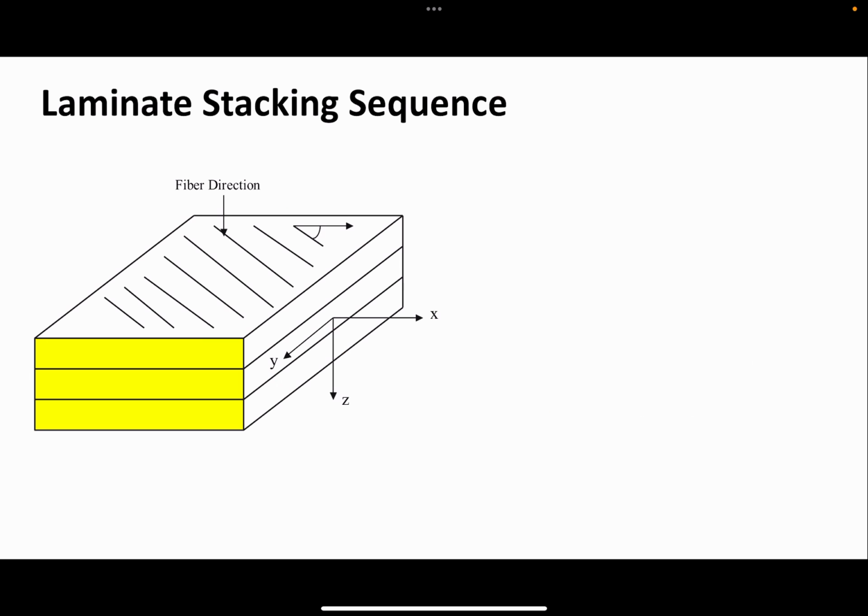What happens if you have an odd number of plies, where you have 0, minus 45, 60, the 60 does not repeat, minus 45 and 0? It is still symmetric about this plane, correct? So then what do you do? Same technique, 0, minus 45, slash 60, but over the 60 add a bar, then close and say S. It means in this symmetric laminate 60 is not repeated.